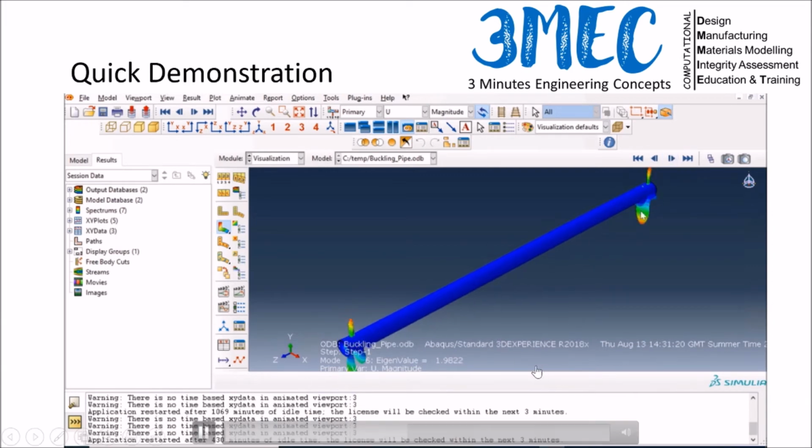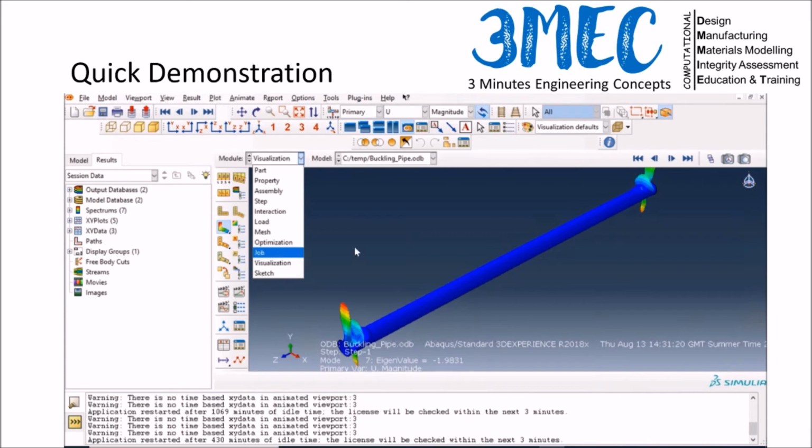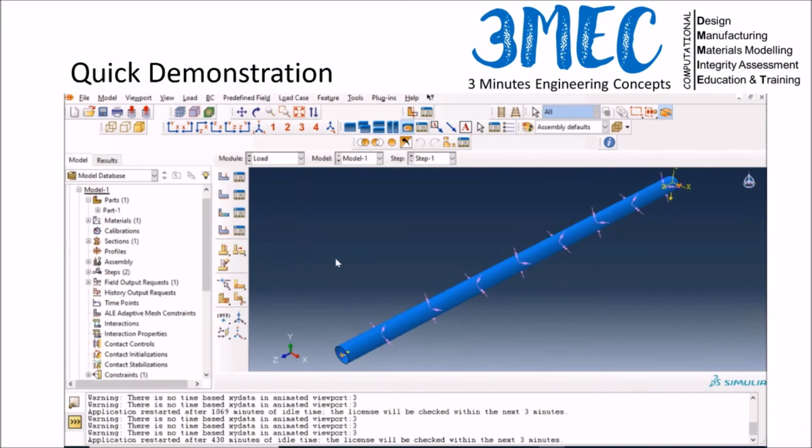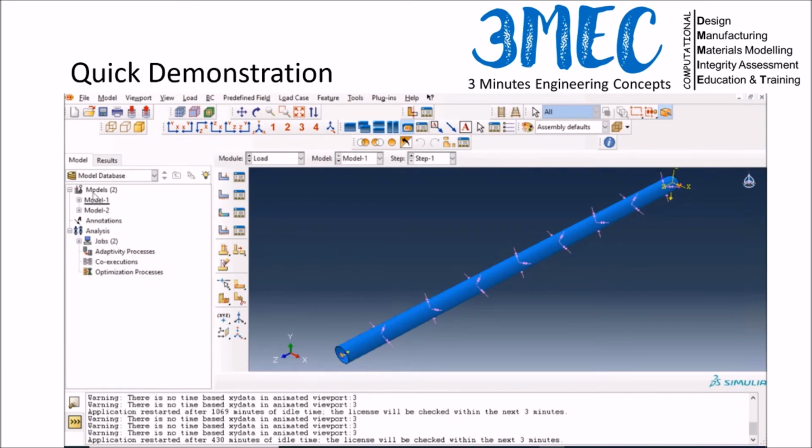Again, you see here some negative values, and these negative values or some eigen modes will mean that if my loading condition gets opposite, like for example internal pressure is lower than the external pressure or force direction changes, then my eigen mode can be in the opposite direction. So this could happen in that case as well. So I'm going to go for the first mode in this case.